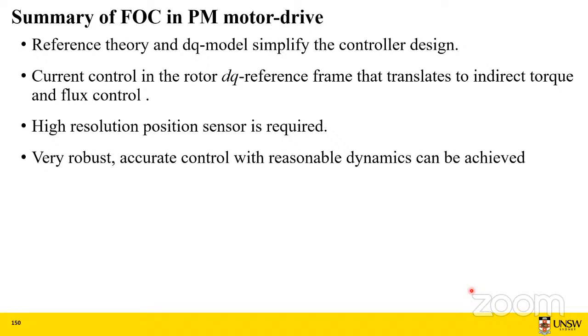And we control the torque in FOC by indirectly controlling it through the current. But one of the things for FOC is that you must have a position sensor, and a very precise position sensor is required, as we have to apply our Park transformation or inverse Park transformation. But it gives very good dynamics, and you can accelerate your motor as fast as you want, and it is quite smooth control. Okay.